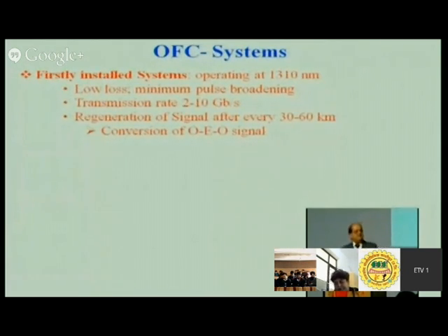At 1550, attenuation is minimum, dispersion is more. So both the channels have their own importance. 1310 is important for high data rate. 1550 is important for long distance communication because attenuation is lowest. At 1310, dispersion is lowest.